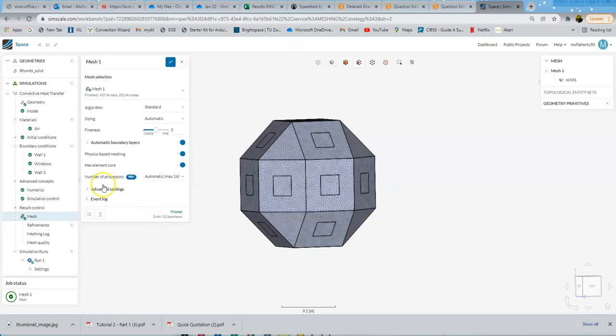After about 2 or 3 minutes, we'll say that the mesh is finished. So we have the tick down here, and you'll see the mesh actually on the surface here. What it's done is break the volume down into hundreds of thousands of little subdivisions, and it solves a simplified form of the fluid equations on them. So it solves them as sets of essentially hundreds of thousands of simultaneous equations, which computers can do extremely quickly, as I'm sure we're going to find out in the next while.